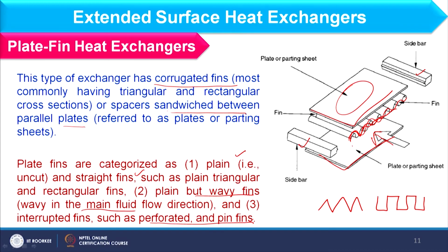Okay, so because of this perforation or pin fins we can have more turbulence, so we can increase the heat transfer coefficient. Okay, now the point is where I am using these fins. Okay, and what I am saying is that extended surface, where I am finding lesser heat transfer coefficient, there we are considering plate fins, because we are increasing the heat transfer area in that particular section. Okay, so it is called the extended surface because we are extending the heat transfer area in a particular region.